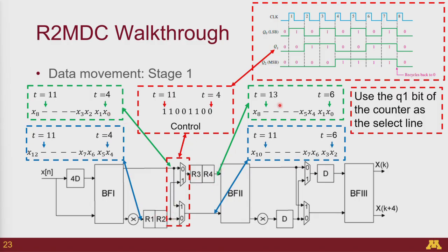So now if you see the output at this stage at time t equal to 6, you would have x0, x2, x1, x3. And by the time x4 and x5 pass through these registers, that would be time 8 and time 9. So is it clear how we can use the delay switch delay to align the data to what we need?